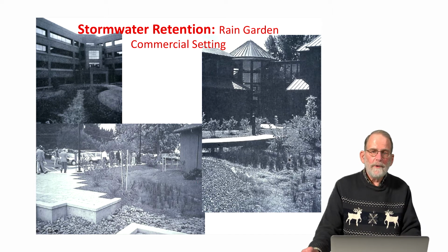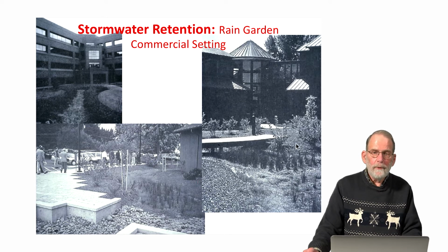The bioswale is constructed of very porous material, which promotes high infiltration. Consequently, we're reducing runoff volume and we're reducing the rate of runoff very significantly. Landscapes such as this can have runoff coefficients very, very low, where most of the water is going to be infiltrating and then evapotranspiring back into the atmosphere.